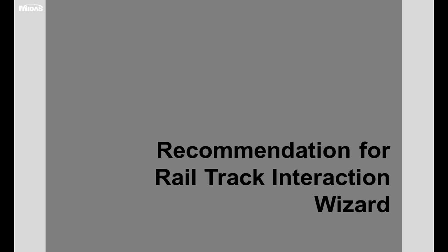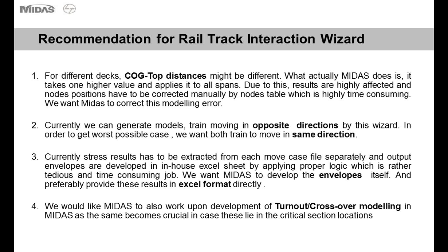Recommendation for rail track interaction wizard. These are some points based on our experiences while we went through the RSI analysis for different projects. So I shall state some requests on behalf of L&D for further development of the RSI wizard in the next slide. The first point, which we also discussed during modeling of projects, is manual correction of COG to top distances, which is highly time consuming. We want Midas to correct this modeling error.